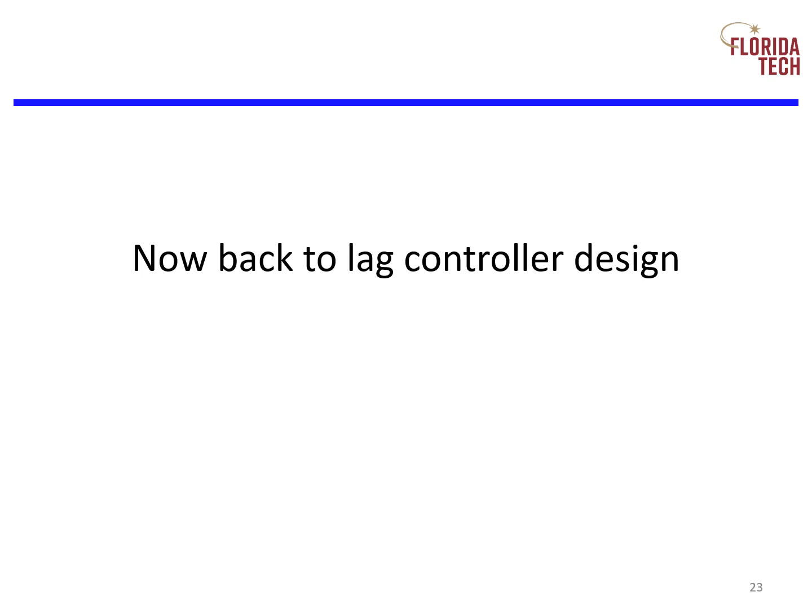With definitions of error constants and knowledge of steady state error, we now can go through the steps of lag controller design. Lag controllers reduce steady state error, but also slow down the system response. But many times in life, slow and steady wins the race. It just depends on the race, or in this case, the design requirements.